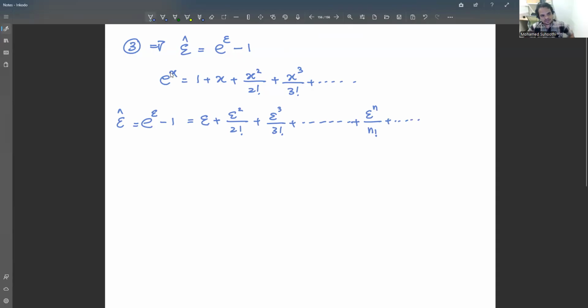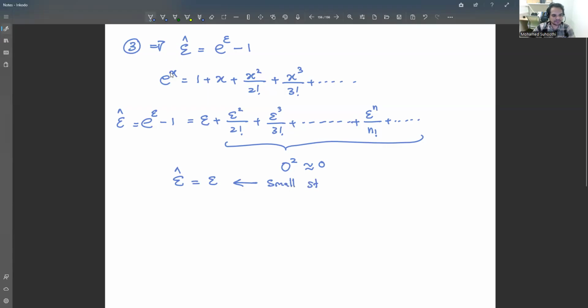Now this is very important. If you eliminate the terms of order 2 and above as 0, what is that? Your true strain and nominal strain are equal, right? So this is only when the higher order terms are eliminated. That means the small strain case, right?